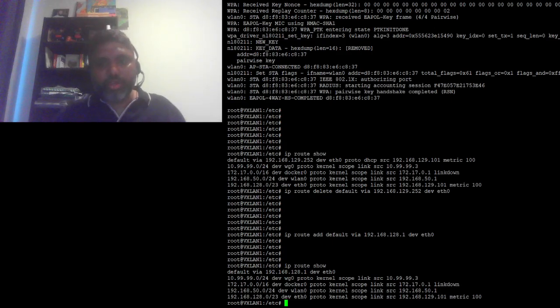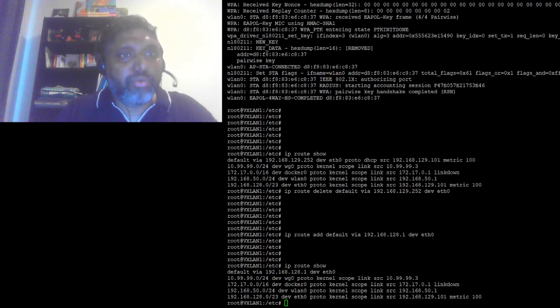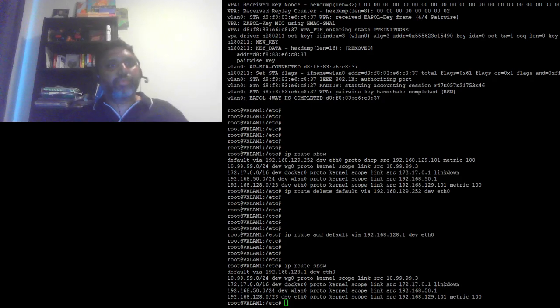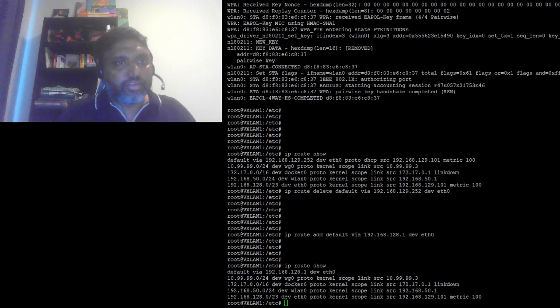So to recap, I will tell you all the steps that need to be performed to enable a Wi-Fi router. First thing is you need to have hostapd installed, right? So for that, do sudo apt update, sudo apt install hostapd, then sudo systemctl unmask hostapd, sudo systemctl enable hostapd. Then you check as part of iw list if the AP keyword is enabled for the Wi-Fi chipset that you are using on the Raspberry Pi.